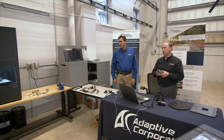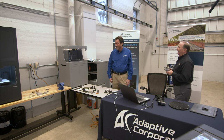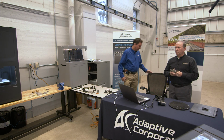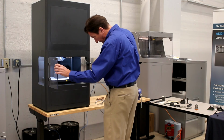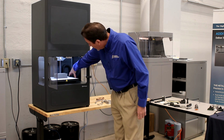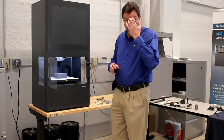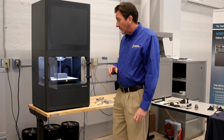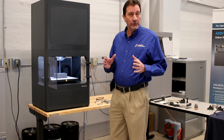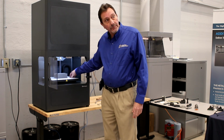What is the bed size of the Metal X? That's a good question. Can we put the camera on the Metal X here? Basically we can see the print bed here. The sheet is actually the size. We overgrow the parts by 20% in the green state, so the actual envelope of a part delivered to you, since it will shrink by 20%, is a little bit smaller than this build platform.